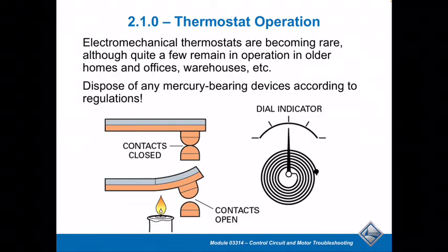Obviously, a room thermostat is designed to control the temperature of the air within a room. Typically you locate them on the wall, outside of the line of sight of any type of heat source, away from a heat source. That means you don't put them over things like microwaves and refrigerators, or next to copiers, things like that.